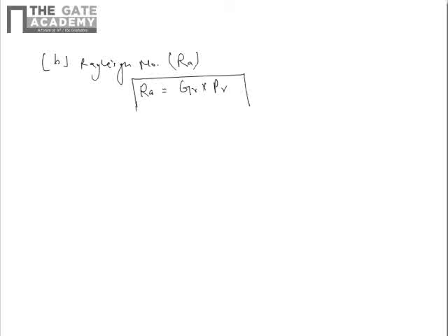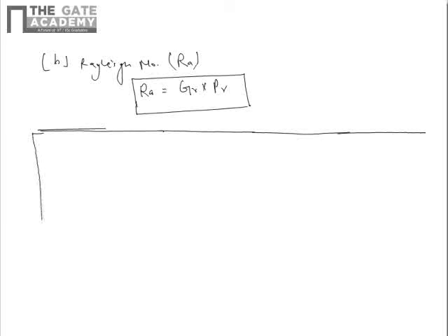The second dimensionless number which is important is Rayleigh number, denoted by Ra. So the Rayleigh number is nothing but Grashof number into Prandtl number. Okay, so in this portion I will give you some empirical formulas to calculate the Nusselt number.